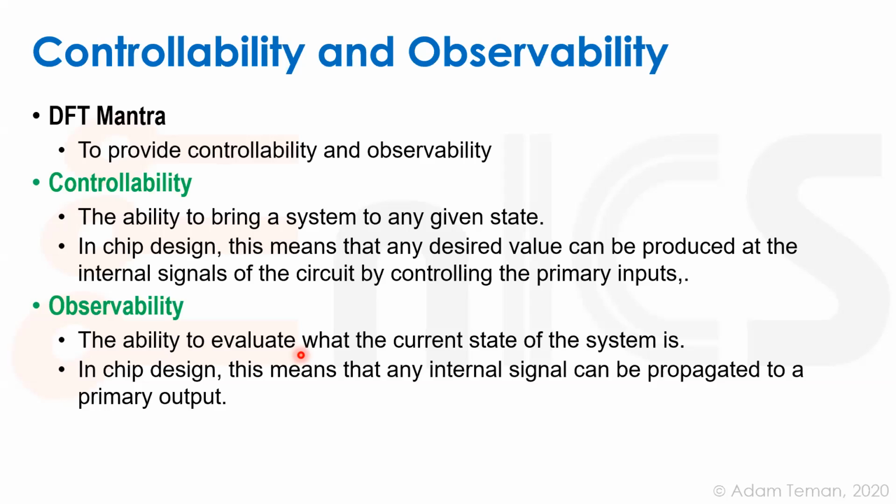If we have an AND gate, and we know that there are 2 input pins and 1 output pin, we have full controllability and full observability. We can put anything on the inputs. We can see the output. Our life is good. That's actually true for most combinational circuits. So we have a truth table for the combinational circuits. We can put whatever inputs we want, and we can see the output and know for the most part what's on any internal node or most of the internal nodes.